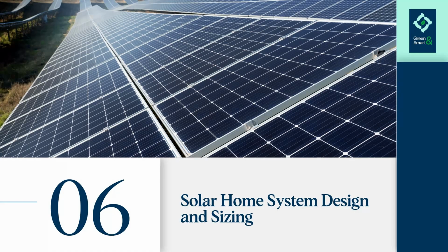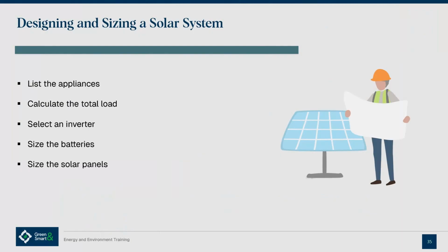Designing and sizing a solar system is one of the most important skills for any installer. This ensures the system can handle the expected load without failing. Here's the step-by-step process. List the appliances. Write down every appliance you want to power, along with its wattage.